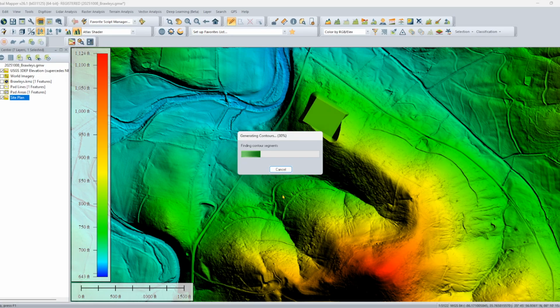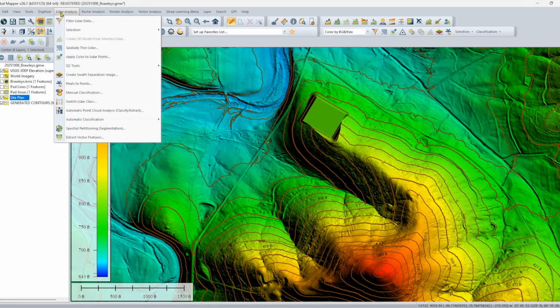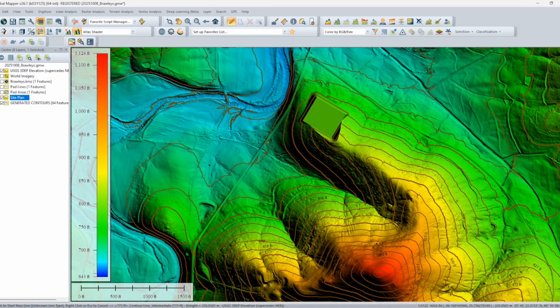Okay, it will take a few moments to create the contour lines, which gives me an opportunity to talk about something, and I think it's important and fundamental in developing this road. Now, the goal here is to draw an access road from the main road up to the pad. I'm going to follow the path of the existing road, so you can think of this as more of a road improvement project than a brand new layout. By staying close to what's already there, I can keep earthwork to a minimum and still get a usable alignment for the road.